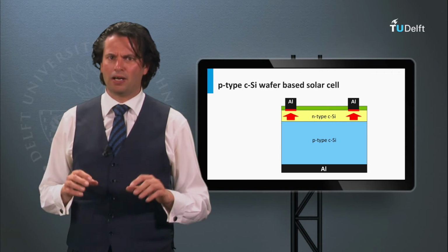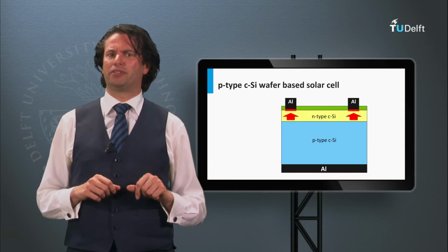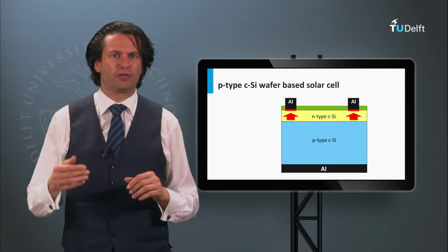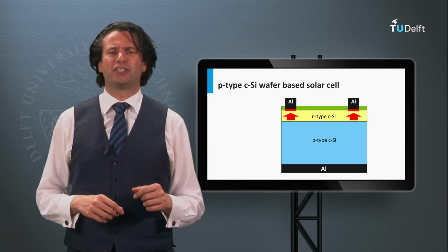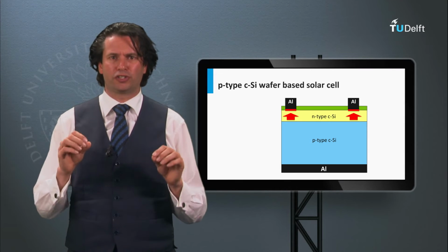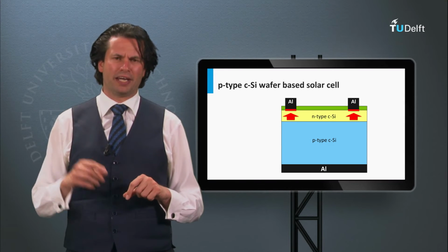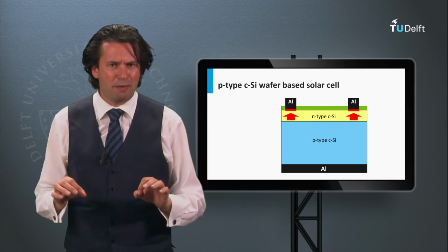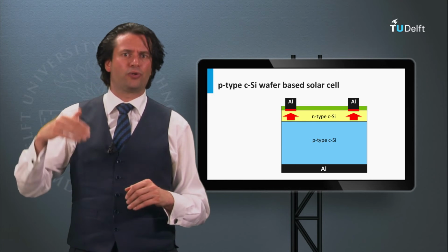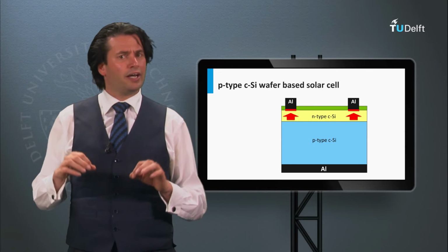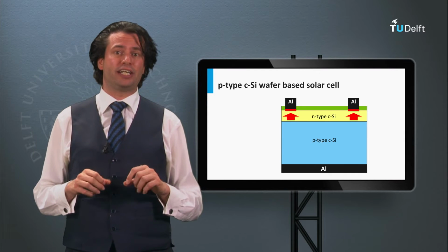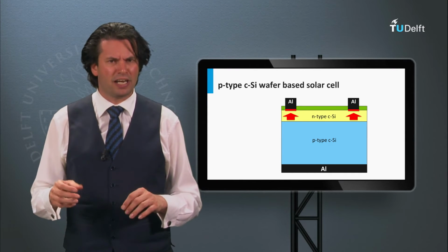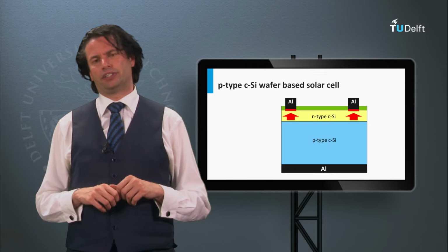In addition, a metal-semiconductor contact induces a barrier for the majority charge carriers. In view of the scope of this course, it's too much detail to discuss this barrier in great detail. Keep in mind that this high barrier will give rise to a higher contact resistance. Again, high doping levels can reduce the recombination velocity at the metal-semiconductor interface and reduce the contact resistance.